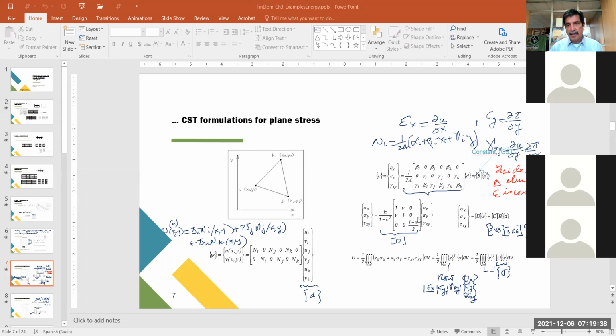If we multiply this vector of the strains times this matrix, in the case of isotropic uniform material, we obtain stresses. Of course, the 3 stresses that we mentioned before. E is Young modulus, nu is Poisson ratio. This matrix, we call it D. So finally, we can say that the vector of the sigmas is equal to matrix D times vector epsilon. And this vector epsilon from up here is equal to the product of matrix B times vector d. Right. So this is an expression that we recall from ship structures, that's last semester.